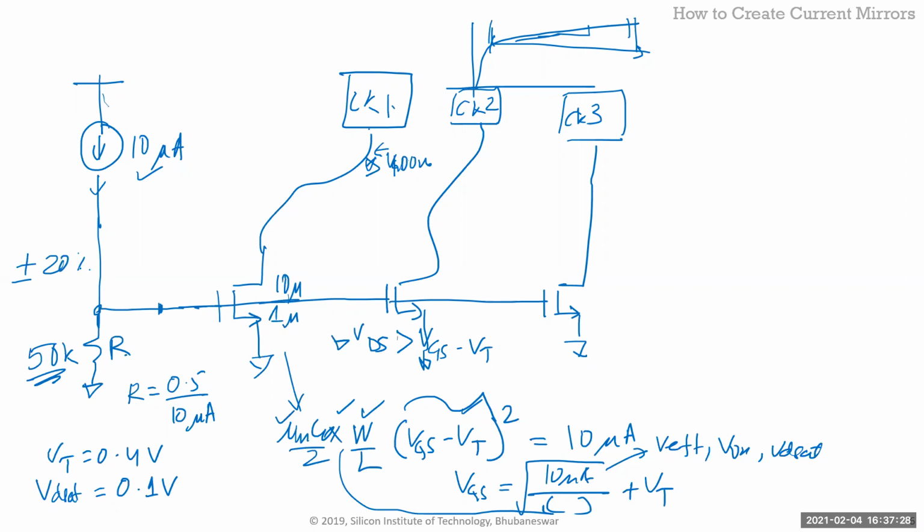In other words, you took the row, you decided what should be the W over L, you created a nice 50K resistor, you plugged it in, you get one part, it's 40K, you get another part, it's 45K, you get another part, it's 55K, you get another part, it's 60K. It'll just vary, right? It can vary all over the place from process to process. Temperature, you do from minus 40 to 85, your consumer, that itself will make it vary by almost 5%, right? So that variation is huge.